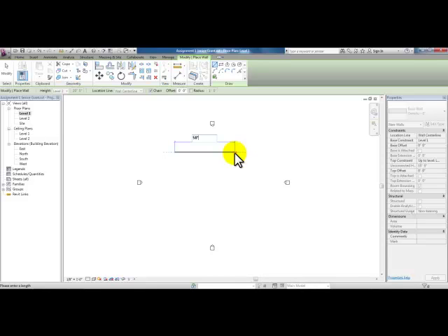In Revit, if you don't type the feet in and you just type in 50, it would be 50 feet. In AutoCAD, when you type in 50, it's 50 inches. So in Revit, remember that you'll need to type in the inches all the time, or the default without inches or feet is going to be feet. So pull your mouse down and type in 50 or 50 feet and enter.